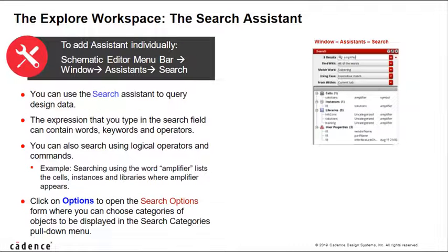The Search Assistant makes your design data searching both simple and productive. The search here uses Virtuoso platform data structures and commands and presents them through an interactive UI, allowing you to define queries based on the results fed back. Precise searches within searches are then possible, as the design data is very structured and generally contains unique identifiers for netlisting and back annotation purposes.